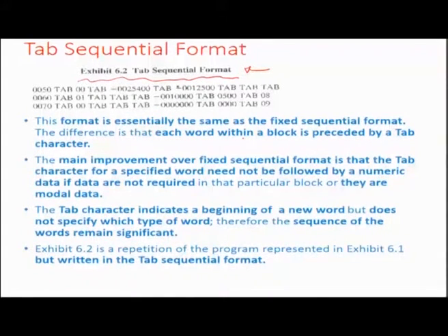In this particular format, the only difference is that whenever there is a change between the previous line and the next line, you need to enter the change. For example, there is a change in the first number from 0050 to 0060, so you enter the change, and in order to ensure that this column is no longer the active column, you use the tab key on your keyboard so that the cursor can go to the next column right here. In the next column you put the preparatory function for the machine axes to start preparing to move ahead. Again, depress the tab key on the